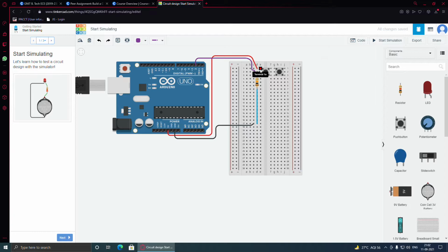Okay, so we are using terminal 1A. To terminal 1A we are connecting power. By power we mean that we are connecting it to the 5 volt standard power of the Arduino. This is supplying 5 volt to button terminal 1A of this push button. From the adjacent hole to which terminal 1A is connected, we are connecting a red wire and taking it over to the 5 volt pin of the Arduino.